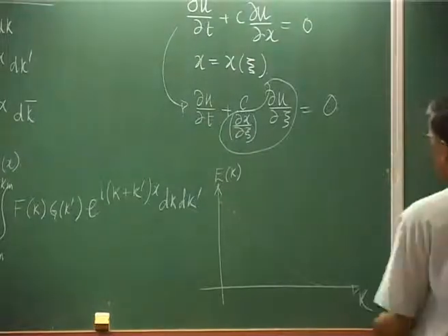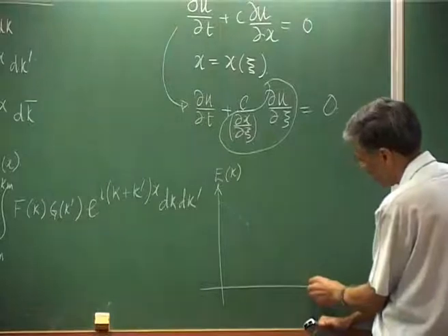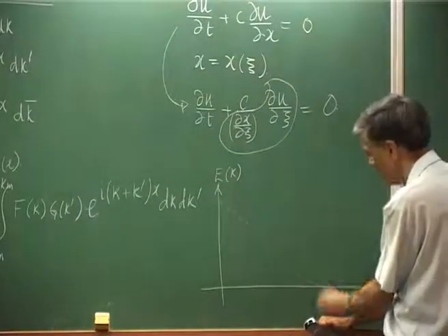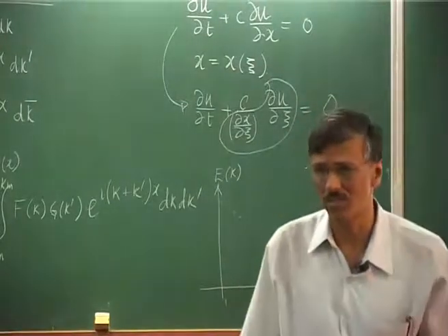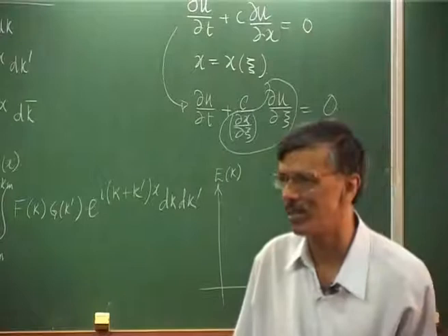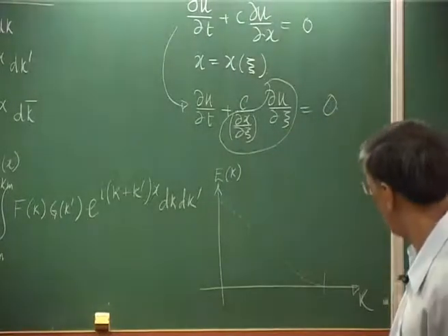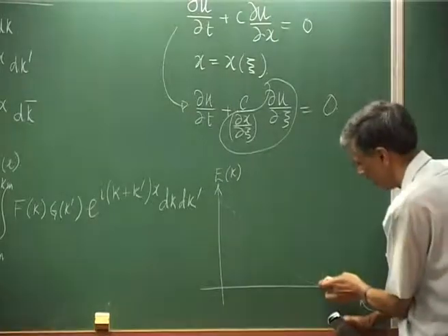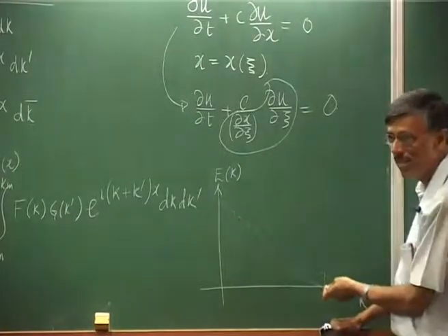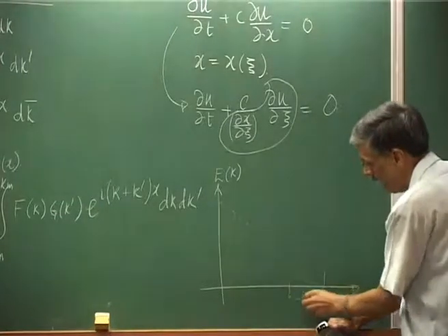You know, there are all kinds of subtleties, and different systems show different variation, but eventually they are kind of band limited. They come and stop somewhere. If you are trying to compute some such system, and if aliasing is present, what would you hope to expect? It is not a good thing to happen, but if aliasing is present, those aliased components will start piling up in the higher wave number range.